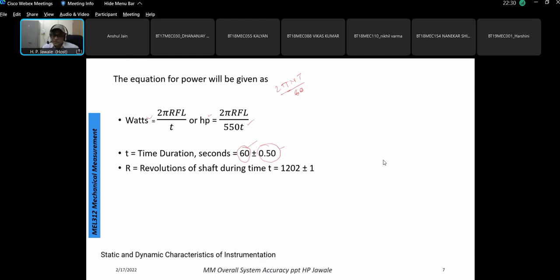So when we are going to take the measurement, we also have understood how many errors there can be. Say if it is a contact type of tachometer, we are going to load the instrument, we are going to load the motor. So because of the load step, there is some decrease in the speed, and it will take some time to pick up the speed variation. And after a certain point of time, it will be showing the equivalent or proportional speed. So there may be different errors incorporated into the number of revolutions that has been measured.